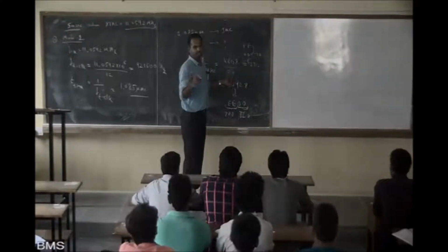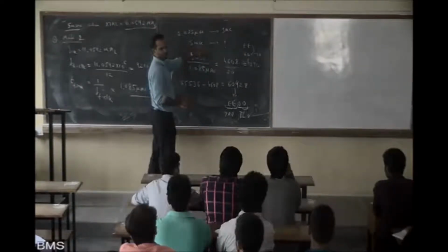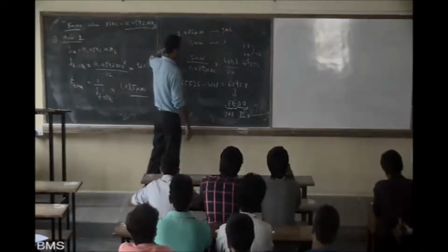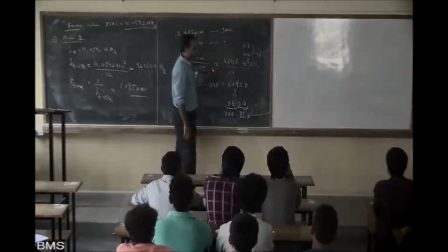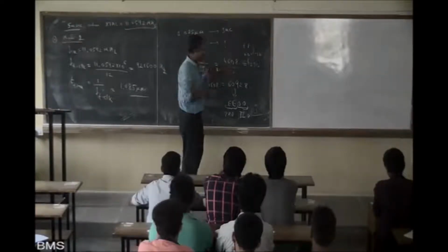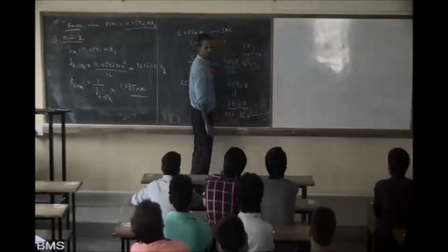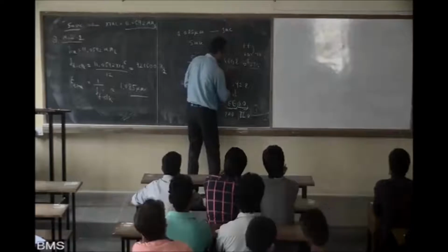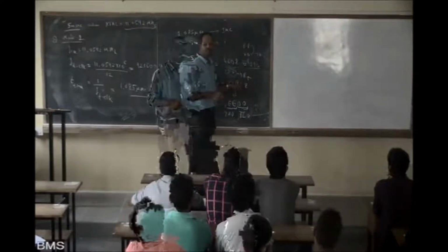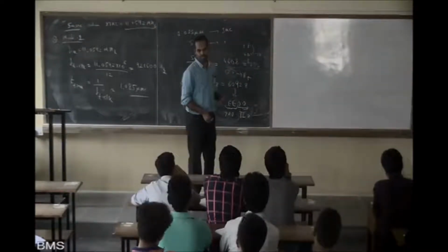Okay, listen to this. Till here the calculation remains the same, whether you use mode 1 or mode 2, it does not matter. What is important here is the given count will not fit in the 256 FF value. So we divide it by 20. So the count value is 230 now. This 20, I will put it in R5 and use it as DJNZ 20 times. 230 in hexadecimal is what?